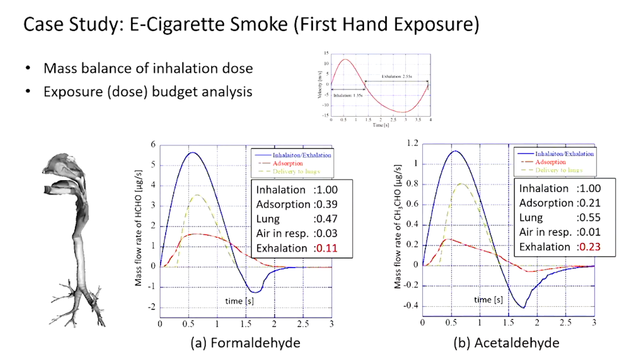This is a completely different value from the previous one I reported, because this one uses the PBPK model as a wall surface boundary condition. The previous result just adopted the perfect sink condition, zero surface concentration. And the surface concentration has a strong impact on the results of these types of simulation. In this analysis, 11% of inhaled formaldehyde is estimated to be exhaled. And this is a new emission source of contaminant in indoor environments.